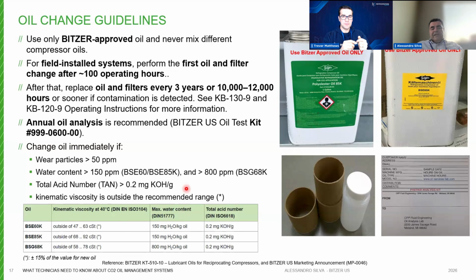If, for example, the system has experienced multiple motor burnouts or motor failures and the oil is very acidic, we recommend changing the oil and also changing the filters.